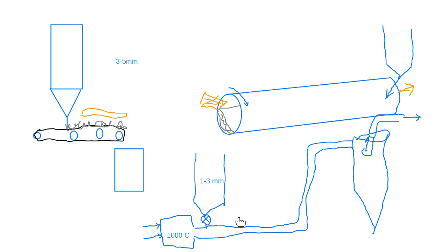But for these particles to actually fall into the pipe, you've got to have a little bit of a horizontal section going into the cyclone, but mainly you would want to use the vertical section, because the biggest particles will be transported slower than the small particles. Small particles will be transported at the speed of the gas, and the big particles will be transported slower because of their terminal velocity in the gas. That's good, because the bigger particles need a higher residence time for the heat transfer from the outside of the particle into the middle.